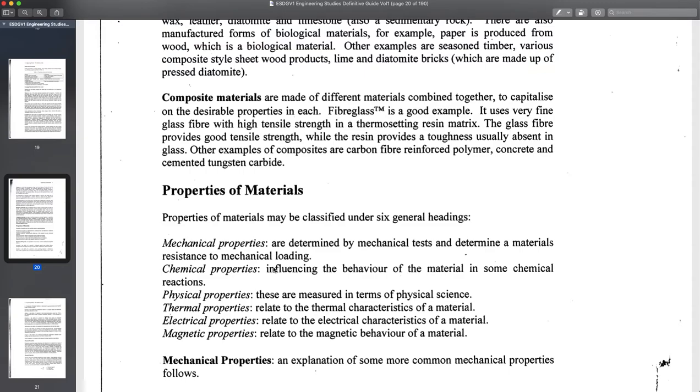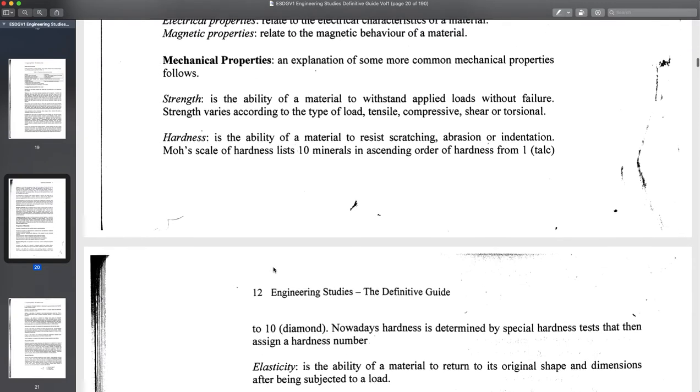Also, if we want to make wire, well, we don't want wire to be all sloppy and moving around, right? So we want to have that hold its shape. But that's not malleability, that's ductility. Now, because of the way that we do our testing, we tend to use the term ductility way more than we use malleability. That's just because of the way that the scientists who do material testing tend to work, right? So we tend to use ductility, even though it's probably less common in practice. But we're going to learn about these words. Let's go through it. Okay.